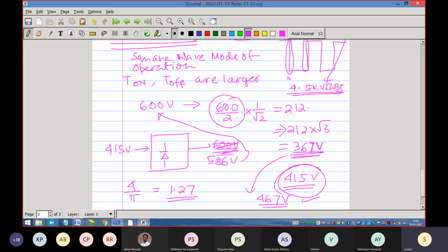But people are crazy, you know. There are a lot of profit motives that also work. Not all the time you can afford to do the best thing that is possible. Engineering is very much compromised by a lot of profit things, etc. So in the traction drive, which carries huge loads, most of the time it is working in the square wave mode. Most of the time, once it reaches full speed, it goes into square wave mode. It operates in the square wave mode. Yes, the machine becomes bad after 3 years, but they have probably calculated that they can replace the machine after 3-4 years.